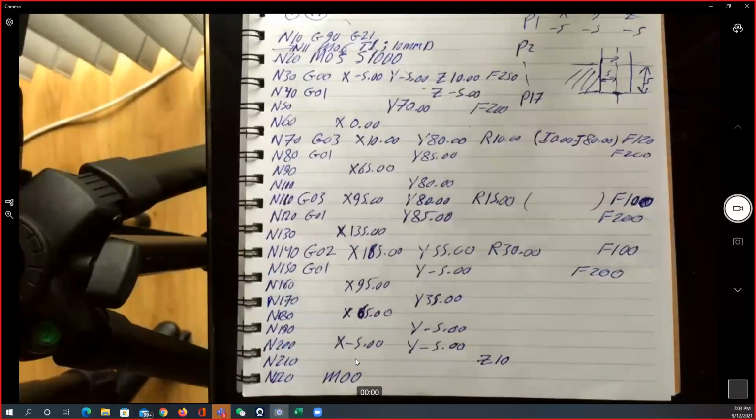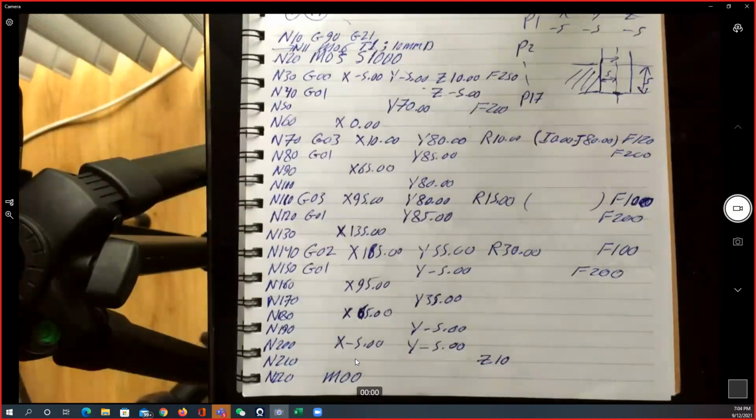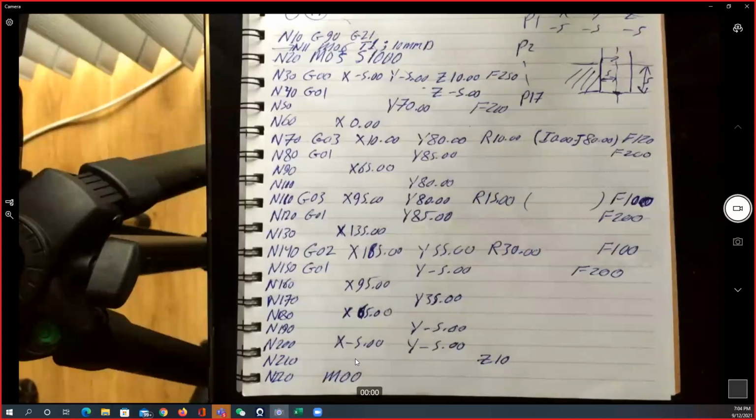Okay, and we're done. Now, if I would like to check the other way around, I will read the code and sketch the points. So I can read the code and sketch the points, and this will tell me what the shape will be again for the toolpath. Undersize it, this will give me the shape of the part I will cut. So it's going to be the reverse way of reading the code.